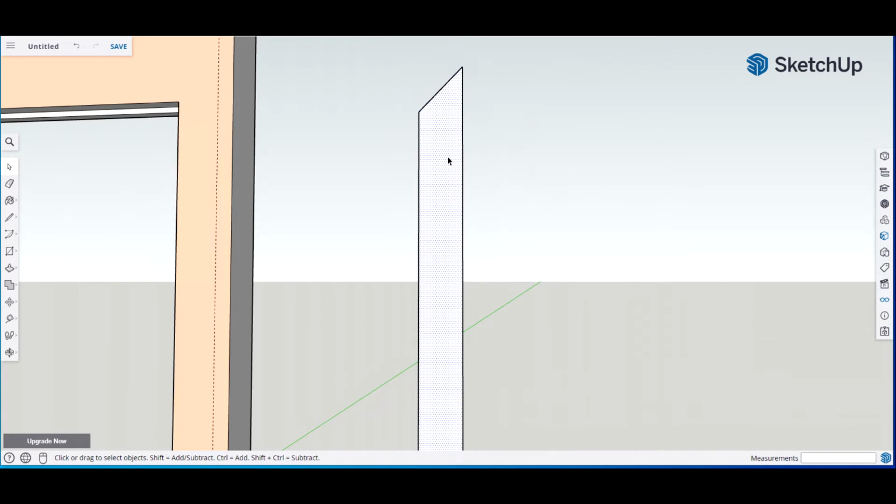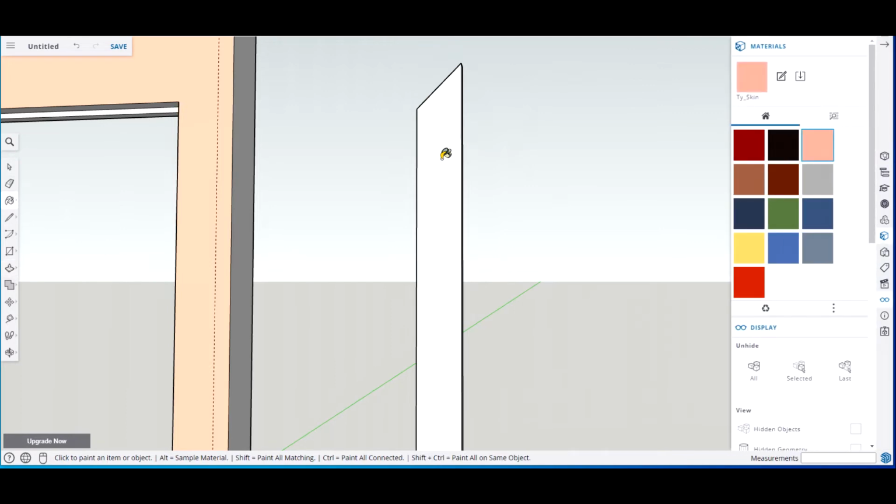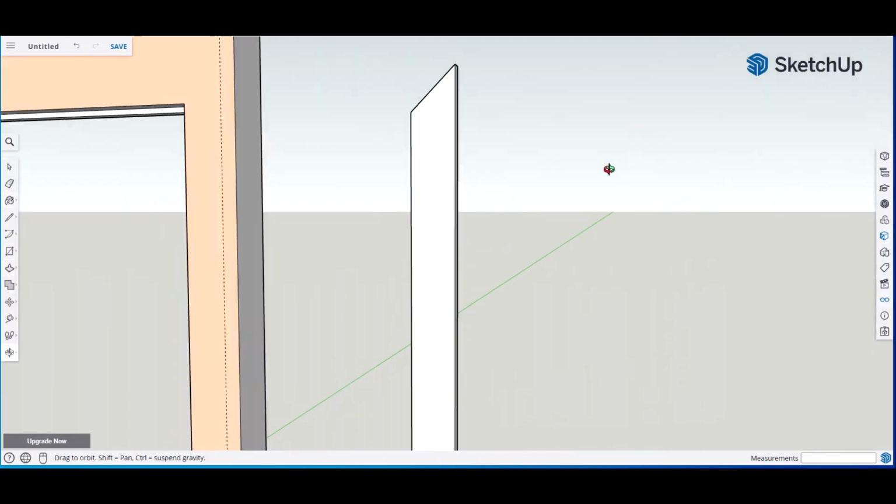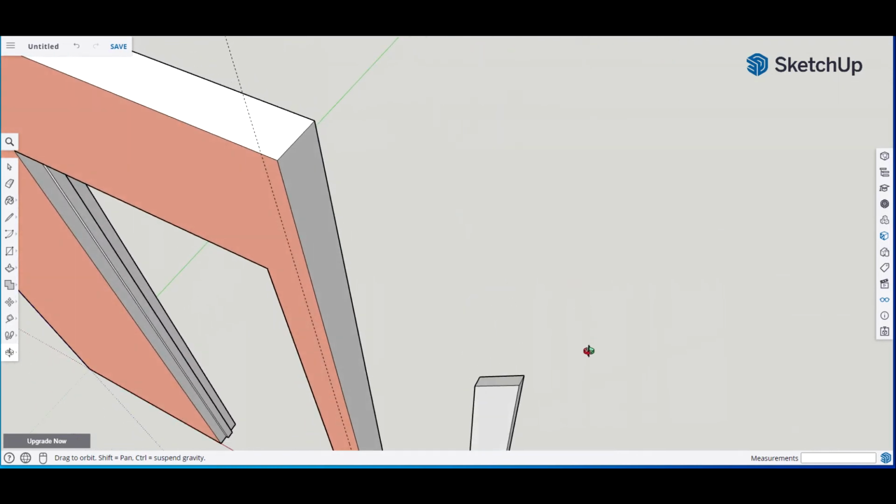Let's go ahead and triple click that and select P, push pull, and the thickness of the molding that I have is 15, close to an inch. So let's put in 15/16 in thickness, space. You don't want to fill it. And it looks good.